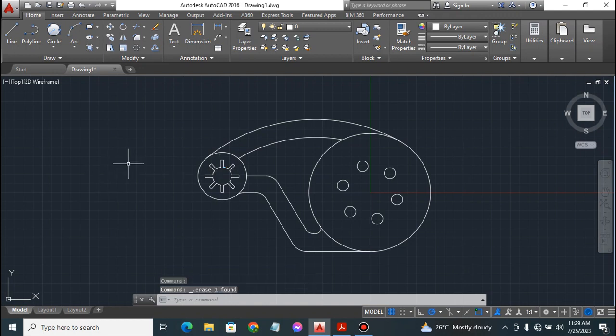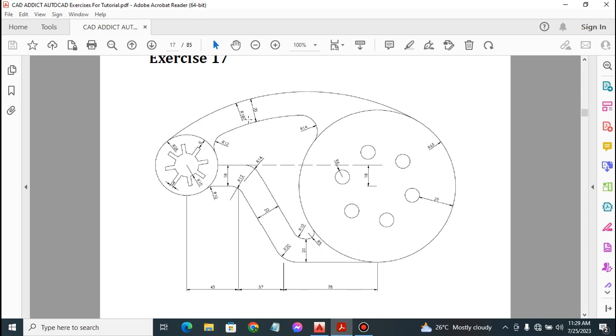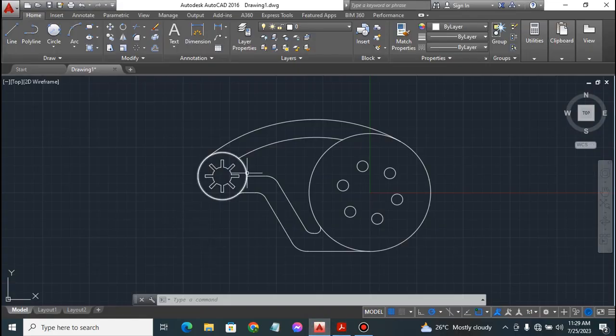So that's it. Next up, from our PDF document, these lines here, we don't have a straight edge there, so we need a curved edge. To do that, we'll still use the fillet tool. But before we do that, let's get the dimension of those curves. At this edge to the right, the fillet radius is 14 millimeters, while to the left the fillet radius is 12 millimeters. So let's go back to CAD to put in those radii.